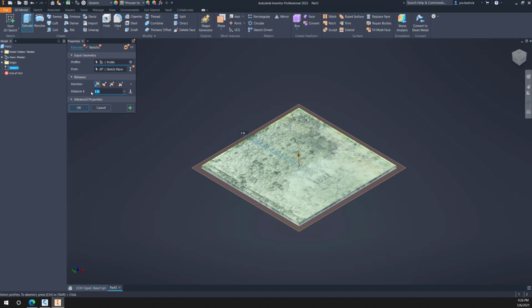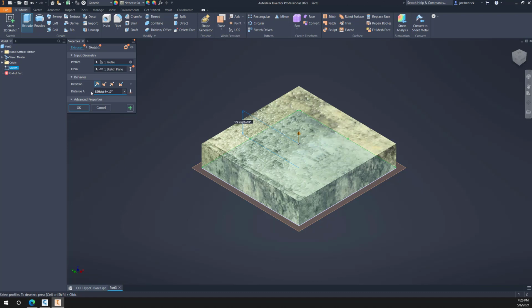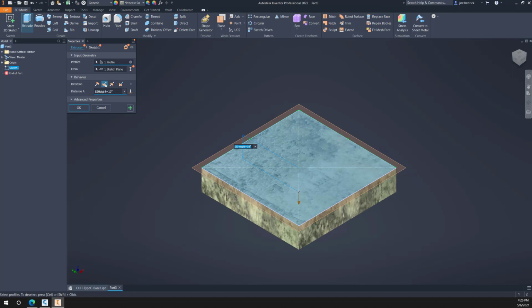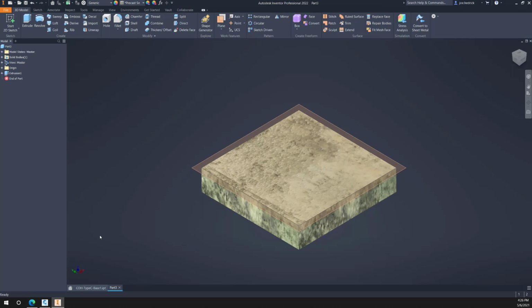It's going to be SS height equals 10 inches. And again, I don't want to extrude up. I want to change because again, I have the best luck starting at the connection and working down from that. So SS height equals 10, right?